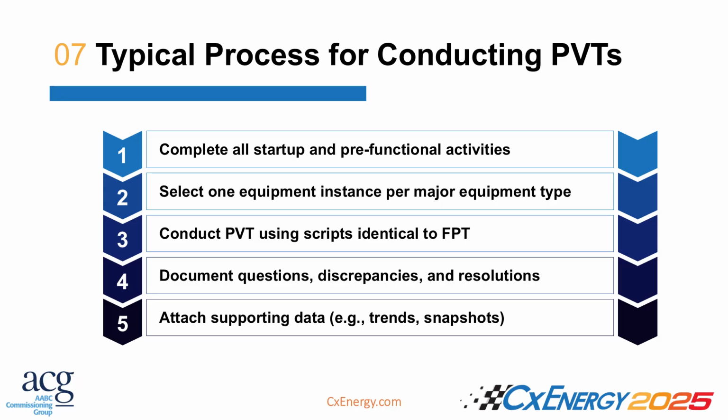Point-to-point verification, testing and balancing, all that needs to be completed. Some of these activities are for the commissioning team to witness, and some are quality control. So all of that needs to be completed, and when the team says, yeah, we're ready, or we think we're ready, that would be a good time to conduct pre-verification testing.